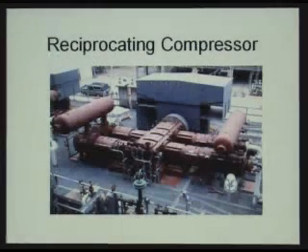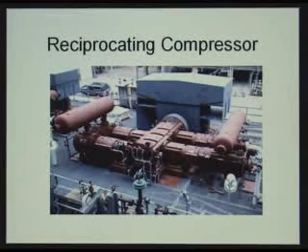Reciprocating compressors. This is a typical installation. There's the family SUV, if you want to get a proportion size. Synchronous electric motor driving the crankshaft, and then this is a 1, 2, 3, 4 piston, or called a 4 crank reciprocating compressor. These stages do the same, and these stages do the same, so this is a 4 crank but a 2-stage compressor.